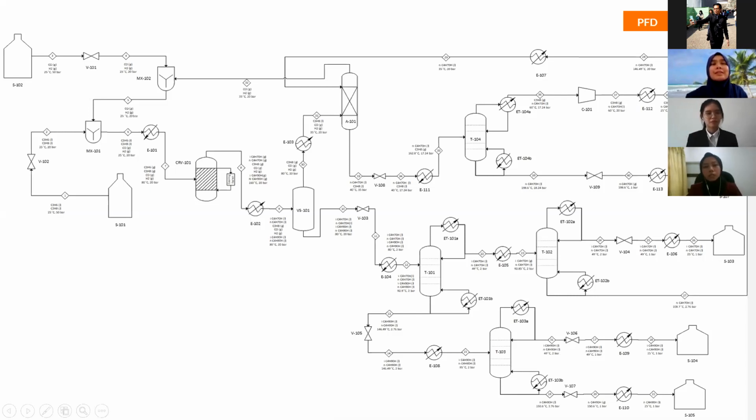Because the boiling point of the propane is negative 42, if I'm not mistaken. So if we are using an ordinary distillation column, we use more energy. But you can just remove propane using just one separator, rather than now you have A101 as your extraction column.